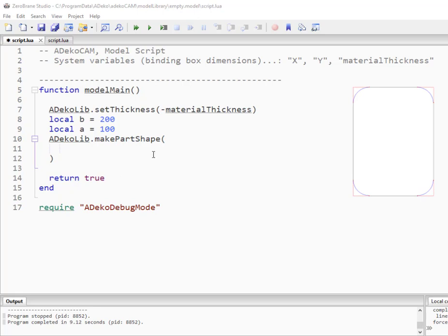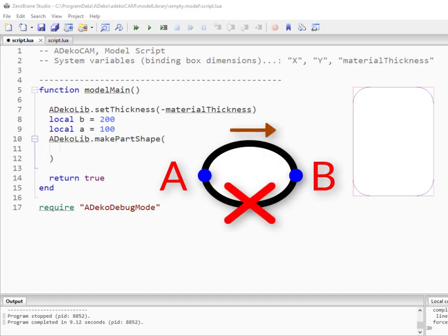Assume we are drawing a line from point A to point B. If the bulge of the point A is 0, the line we draw between A and B is straight, and as the bulge increases from 0, the line starts to curve. The direction of the curvature depends on the sign of the bulge according to the clock. Positive bulge values cause the line to curve clockwise and vice versa.